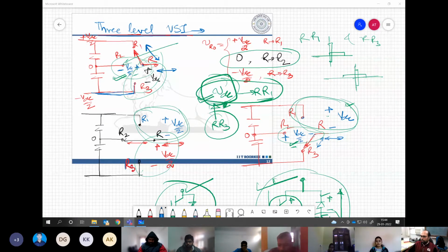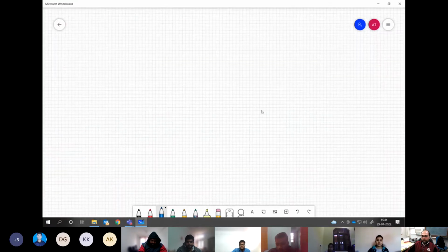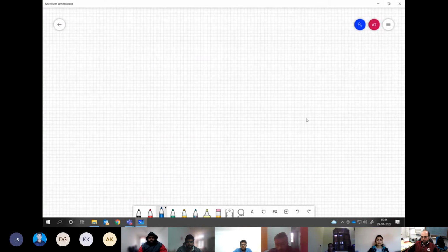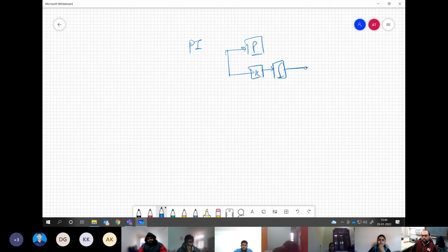Then let us come to the lab exercise. So Ashish Kumar Panda was having one doubt, that how do we decide the limit on the integrators, wherever we have, say, a PI having 2 blocks. One is proportional, another is the integrator, so some gain Ki times the integrator. Whenever you have an integrator, you certainly need some value where you need to stop the integration.